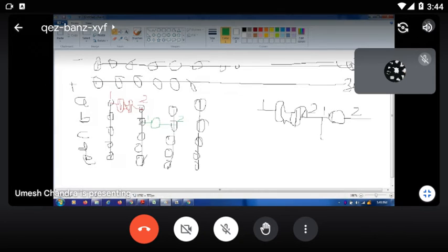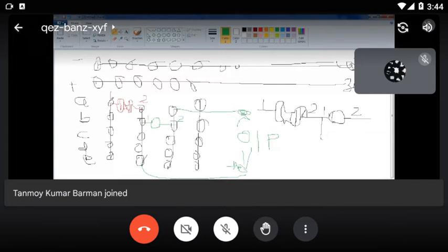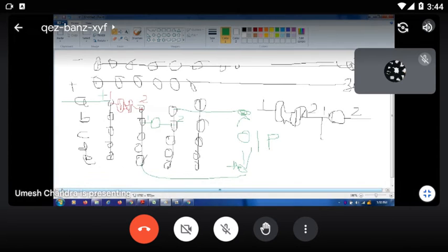Then, where the resistor and capacitor both are connected, that is your output positive. This is the positive of the output. And the other side of the capacitor, that is terminal 2, is negative. And here you connect an oscilloscope for the output. The input is given from the signal generator. This is your positive. And for negative, you connect all the negative terminals at the same potential.